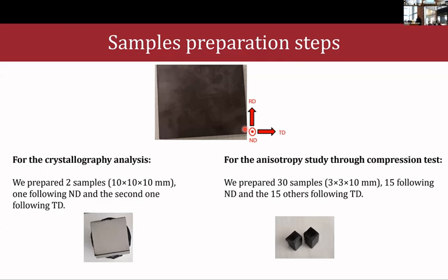Yeah, polishing. Were these waterjet cut? Because I know when it cuts, it kind of spreads out. No, sorry. I just want to point out that, based on indentation, we see a lot of spatial variations in properties, so depending on where you're sampling, some of your variations are just coming from not having consistent microstructures across the plate.